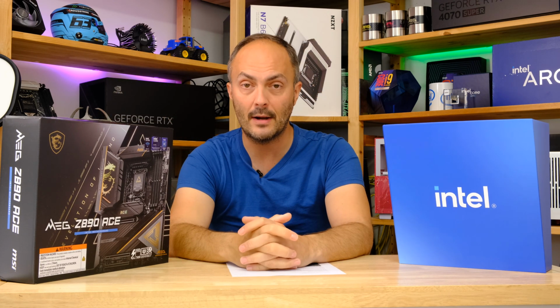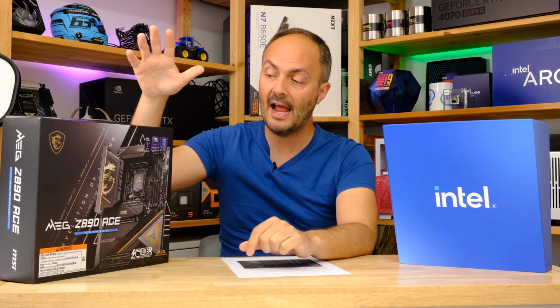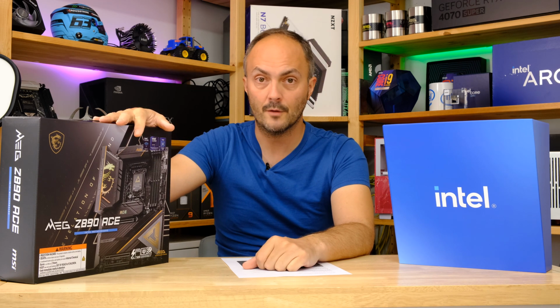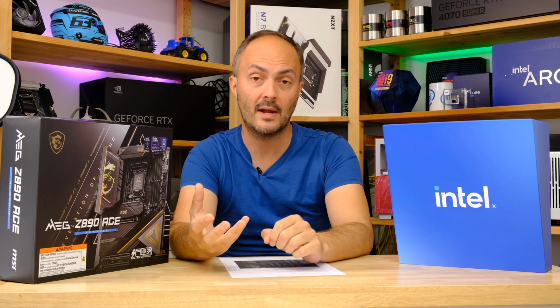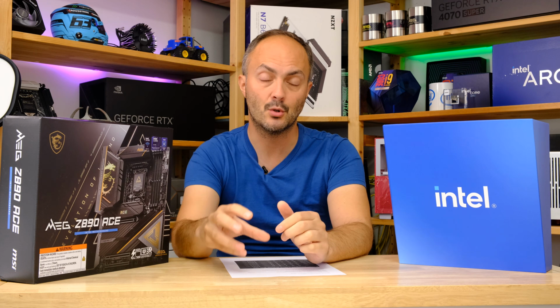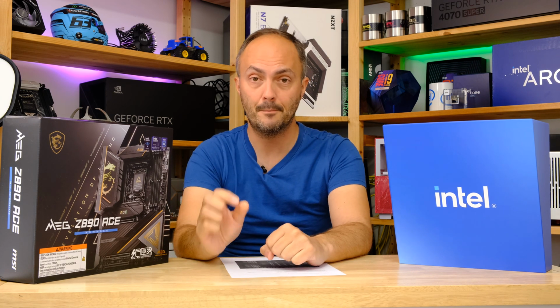And in another video out today, we're going to actually take a look at how to install a Core Ultra 200 processor in an LGA 1851 Z890 motherboard for the first time, to make sure that you guys coming from maybe a socket AM4 system where the pins are on the motherboard actually install it properly and don't end up bending the pins in the socket, because they are super fragile, and bending the pins is still a leading cause of motherboard RMAs.